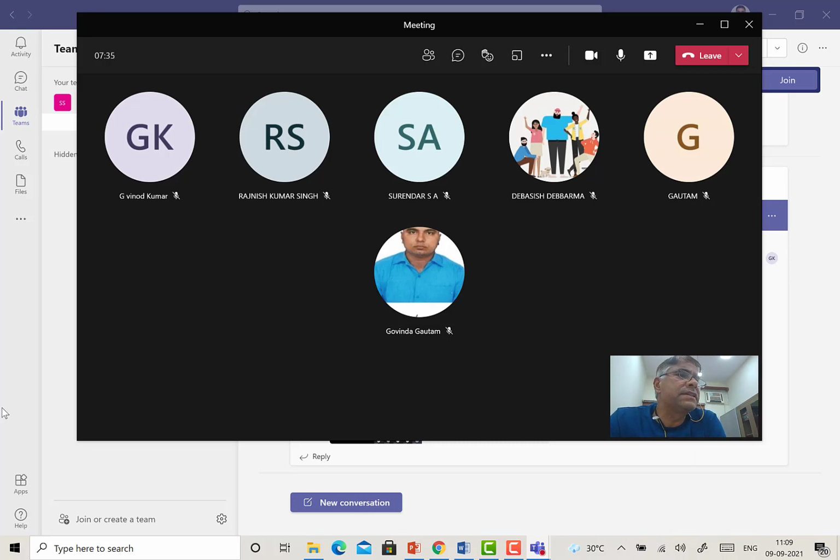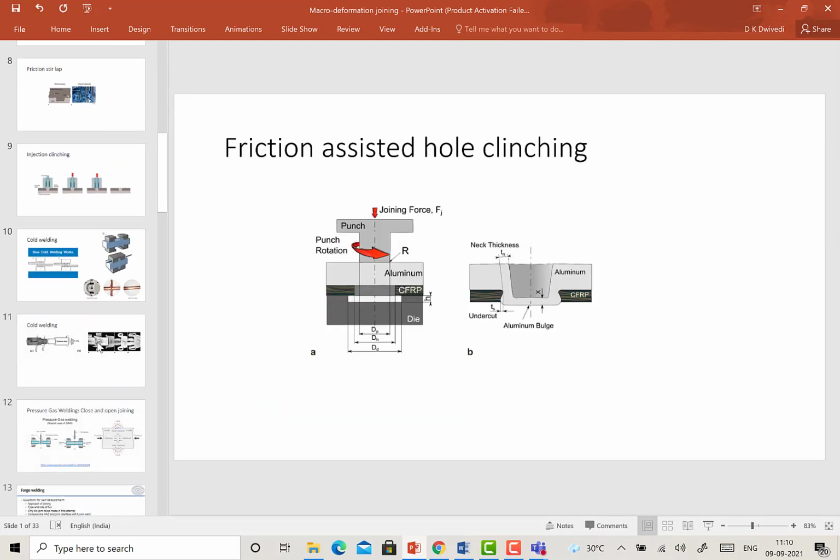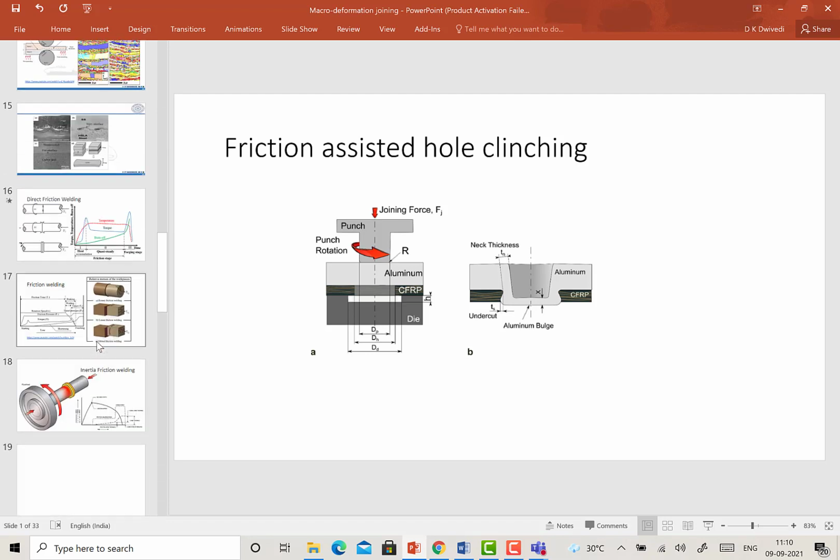Rotary friction welding is most common, but in rotary friction welding various combinations and options are available depending upon the kind of metals, similar or dissimilar, that need to be joined. Thereafter, based on the type of relative motion being applied, whether it is simply rotary, reciprocating or angular motion, some kind of grouping or classification is done. So we'll talk about that as well.